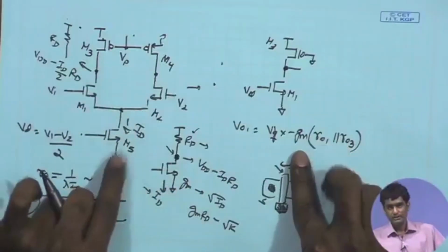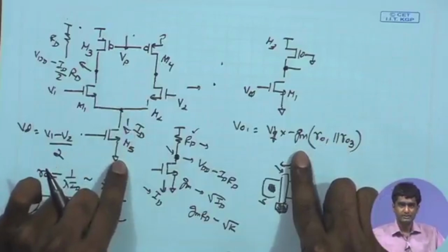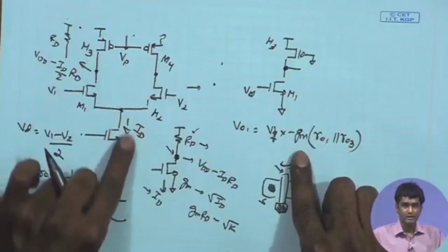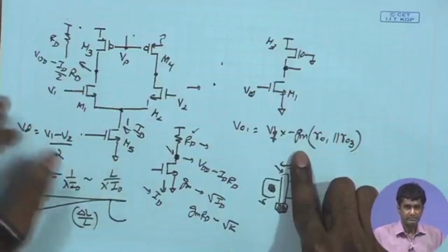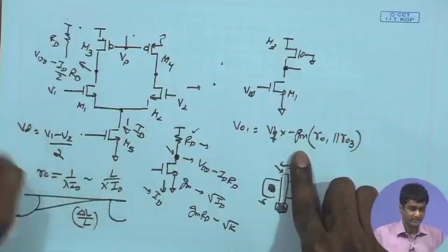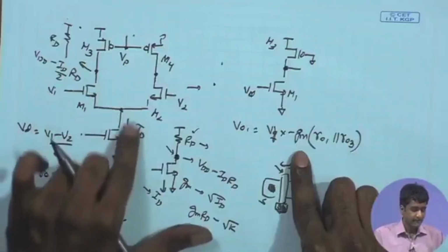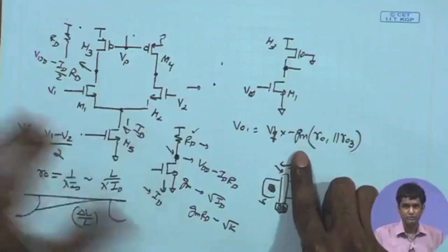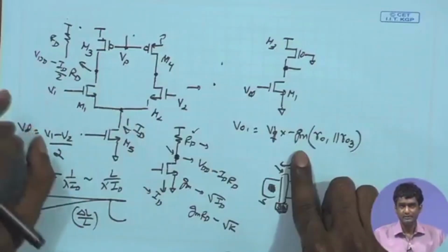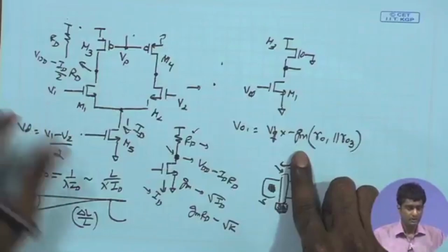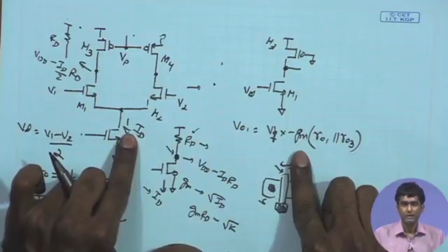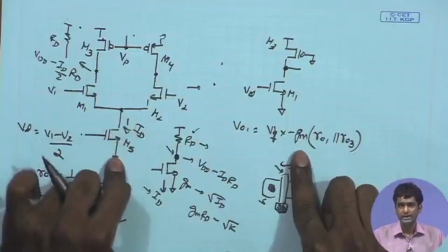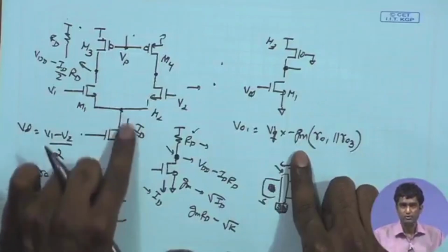So we have to keep that much margin, but still it is relatively well defined. There are ways in which we can define the current source also pretty precisely, and we can have a very well controlled current source. You can have a current reference, as we will see in the course. We can design very precise current references using appropriate techniques. Once you have a precise current reference located somewhere in the chip, you can copy that current reference using current mirrors at different points. If you want more accuracy, you can use cascode current sources and have more accurate control on the current source.